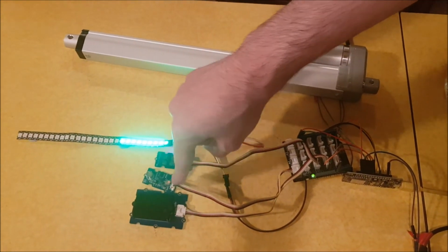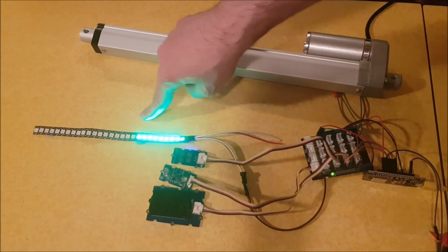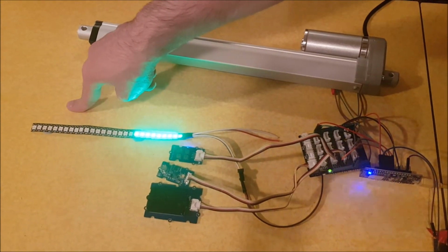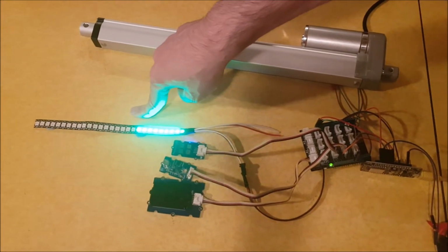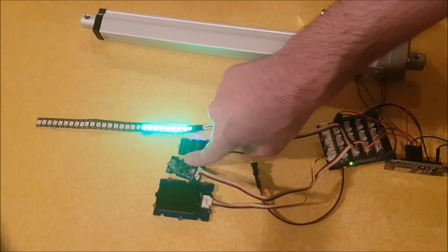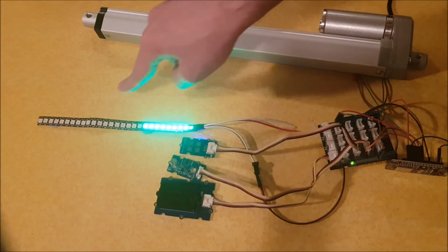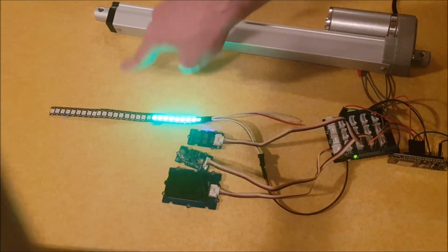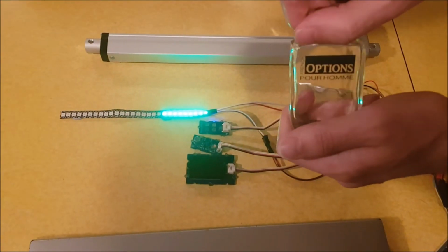When the air quality sensor detects bad air quality, the LED strip will start going sequentially from green to yellow to red. Red determines high pollution, yellow determines low pollution, and green determines fresh air. When the air quality sensor detects bad air quality, it will signal the linear actuator to open the window. As soon as it detects good air quality, it will signal the linear actuator to automatically close the window. We can see this in action here.